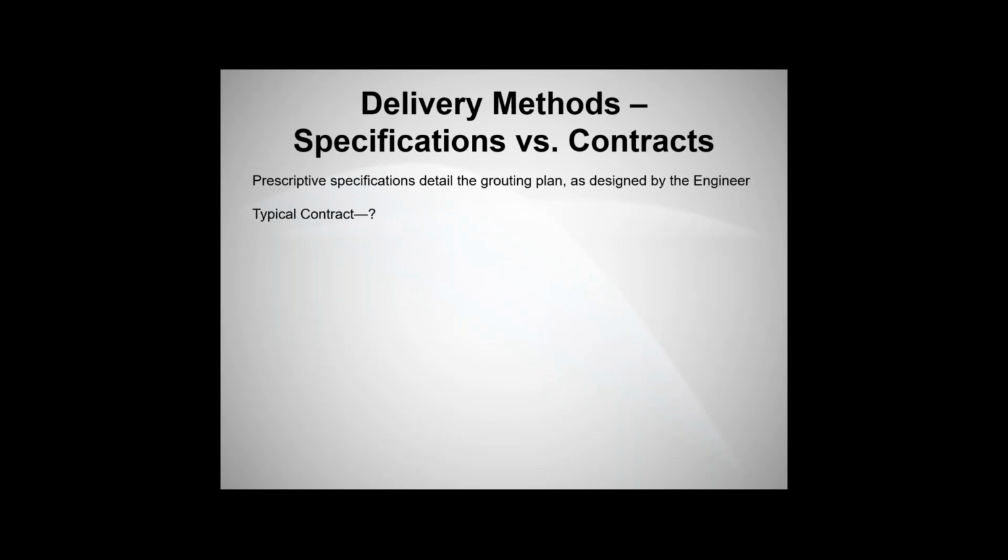Now, part of this is that the risk of the program working really rests with the engineer. Typically, for specifications like this, we're using unit rates to pay for them. So on the design side, we establish bid items. We provide the contractor with estimated quantities: how much drilling, how often is that grout pump going to be running, how much cement can you expect to use, and then the contractor will provide us their unit rates.